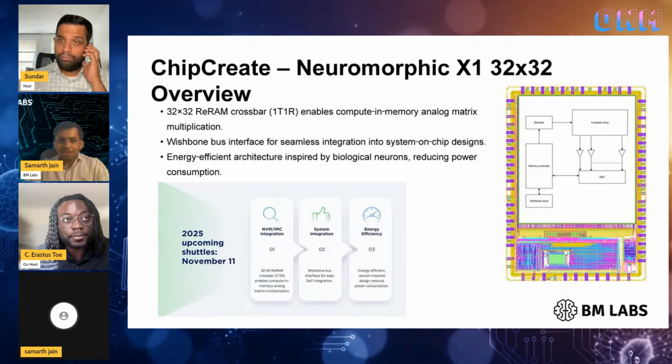That's why we have a digital bus, called Wishbone, available in this IP, which you can directly hook up with the open source RISC-V available in something called Caravel, which I'll be explaining later, right? So you can just take our IP, connect the Wishbone slave available in the IP, which gives you a digital interface, hook it up with the Wishbone master bus in the RISC-V, which is open source, and then you have a full communication and a working SoC available, right?